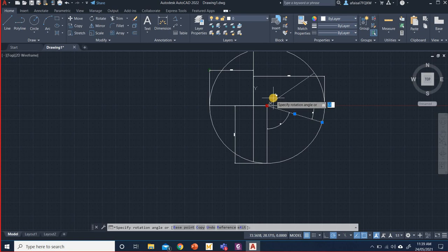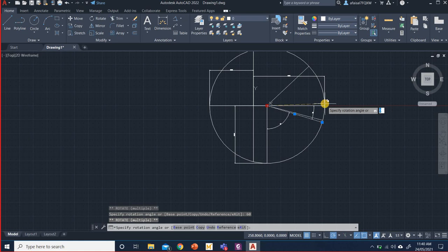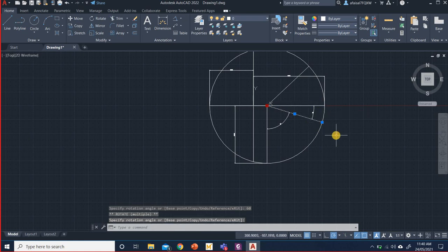अगर ये मेरा वाई नीचे को होता और मैं एंगल इस तरफ चाह रहा होता तो मैं नेगेटिव वैल्यू एंटर करता, ताकि अगर मैं पॉजिटिव एंटर करता तो फिर तो ये मुझे फ्रॉम एक्स टू पॉजिटिव वाई प्लॉट करता अगर वाई नीचे होता ना। अब मेरा वाई ऊपर है, मैं जब 60 एंटर करूंगा तो ये इसी सेंस में एंगल मुझे देगा, ठीक है। सो अब मैं इसके अंदर 60 एंटर करूंगा और अब ये इस लाइन को प्लॉट कर देगा। This is how you can do it.